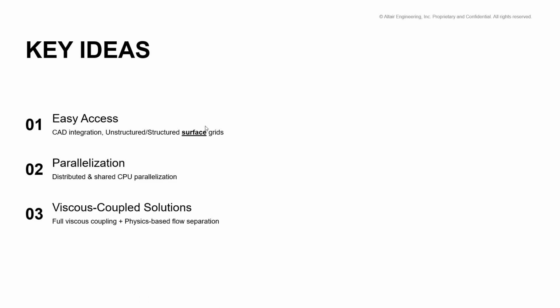And now coming to viscous coupled solutions. For those of you who have worked with panel methods before, the big distinguishing factor is the full boundary layer viscous coupling added, as well as flow separation capability, that allows us to do the boundary layers, drag force, stall capture, and stall prediction, stall angle kind of stuff. So those things you can do with the tool.